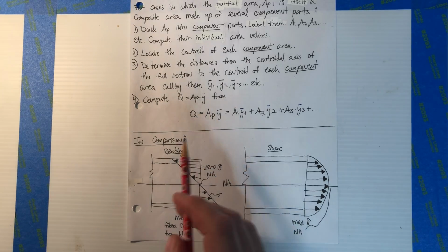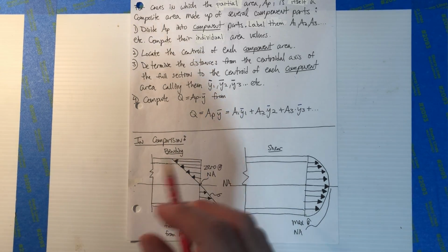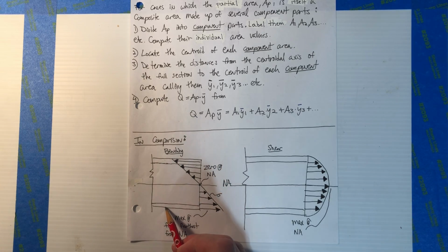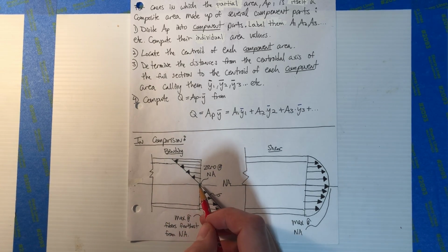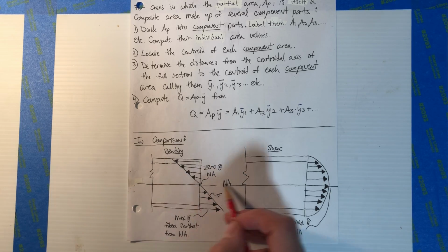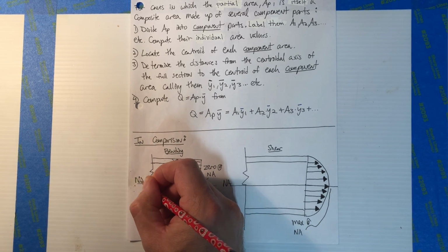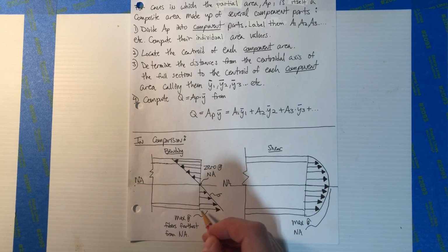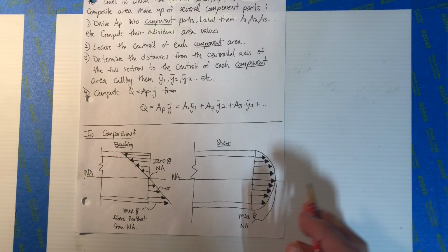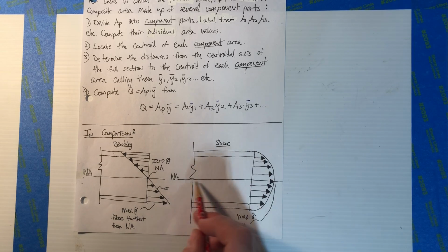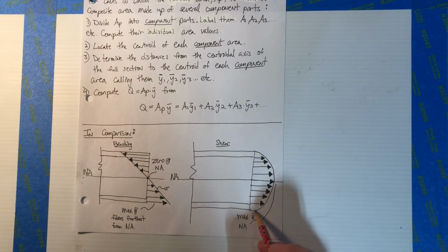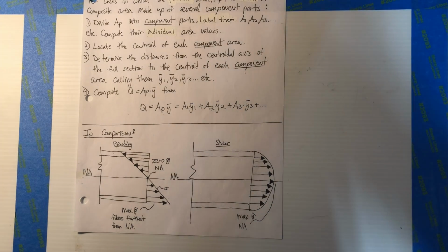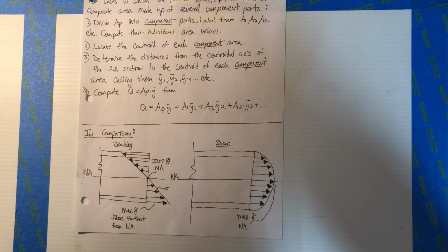And here's, if you did a plot, we talked about bending stress. This is an I-beam looking sideways. Here's the top flange of an I-beam, the bottom flange of an I-beam. Notice if you plotted the bending stress, at the neutral axis right here there would be 0 bending stress, and it's maximum as you get to the end. Shear stress looks totally different. It's actually maximum at the neutral axis and 0 at the outermost fibers. So in theory, in any beam's cross section, if you wanted to find the maximum shear stress, you would always look at the neutral axis.